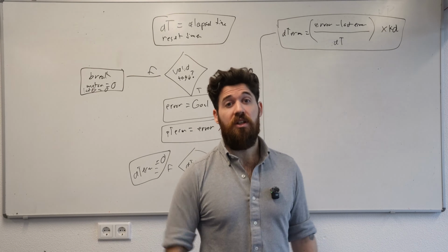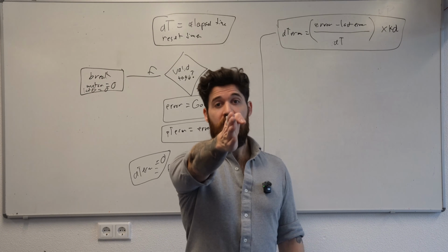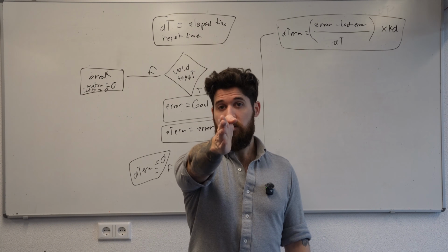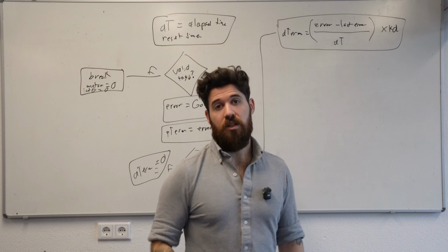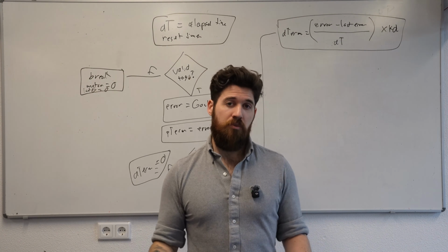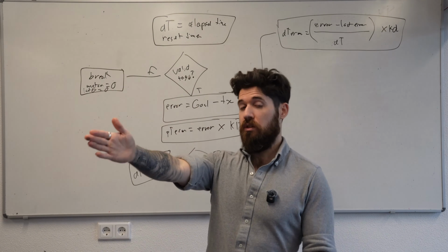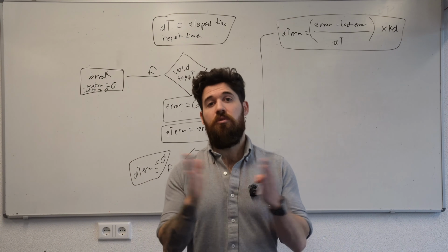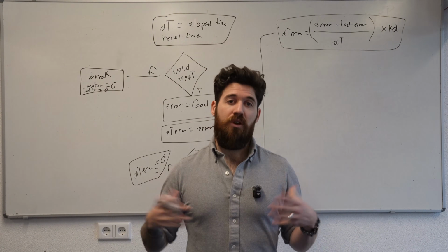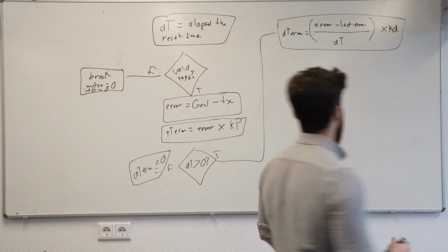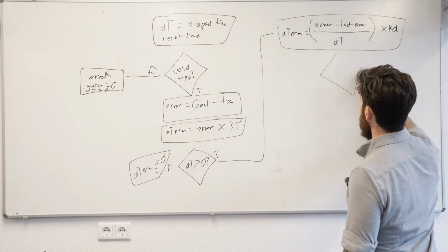So for instance, if I'm looking at the camera right now, you might say this looks directly at the camera. You might say that looks directly at the camera based on how far away I am. That was about a 2-degree difference or a 2-degree tolerance. Whereas we know that if I'm way over here, it's probably too much. So you want to have some sort of a dead banding zone where you're actually happy with that amount of tolerance.